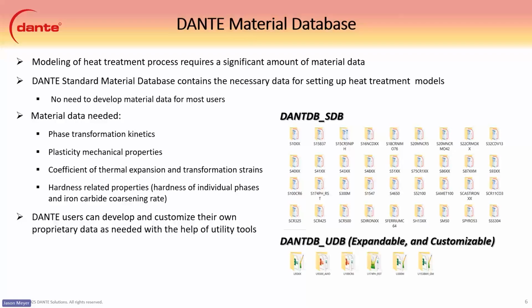Oh, I do have one more. Which kinetics effects, especially on carbide precipitation and austenite formation, are taken into account during the different steps, LPC and austenitizing, through the time transformation stage? Does the software include additional precipitation and diffusion kinetics in the models?